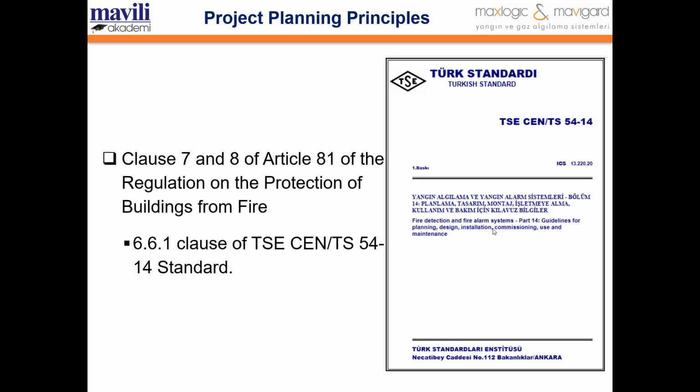Note 1. Fire alarm response strategies differ markedly across Europe, so it is important that they be clearly documented prior to design. Any alarm that must be detected by untrained persons, such as the general public, should at least be made by audible means. These should be alarm devices or an audible alarm device as appropriate.